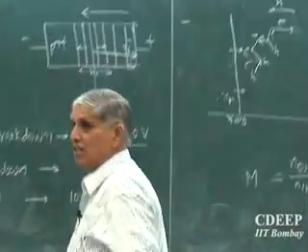So a large number of electrons can be picked up, and a large number of holes from the contact can go to the P side, and you may see again a larger current. Punch through means you have punched the base, that is, depleted the complete base. If you deplete the base, there is no recombination. Remember, the larger the depletion, the electric field here is very large.